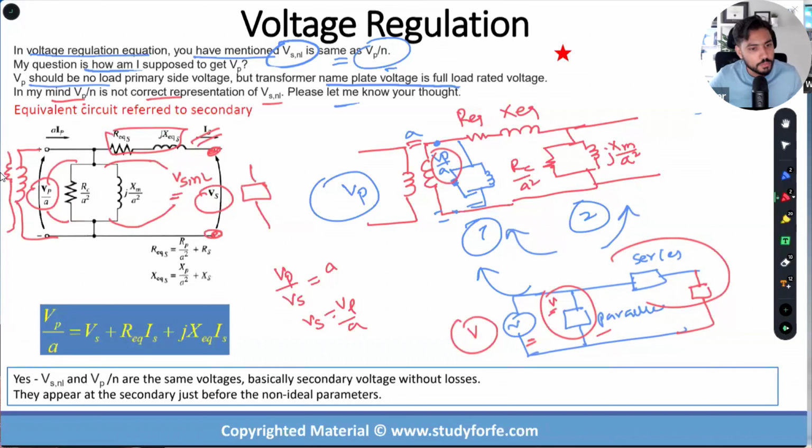All right. So one problem where we have two Y loads and one delta load: if we are using V phase, do we need to worry about the 30-degree phase shift because the handbook is not providing any information? If you have two Y loads and one delta load, you're going to use V phase. It's very abstract on what you're asking.